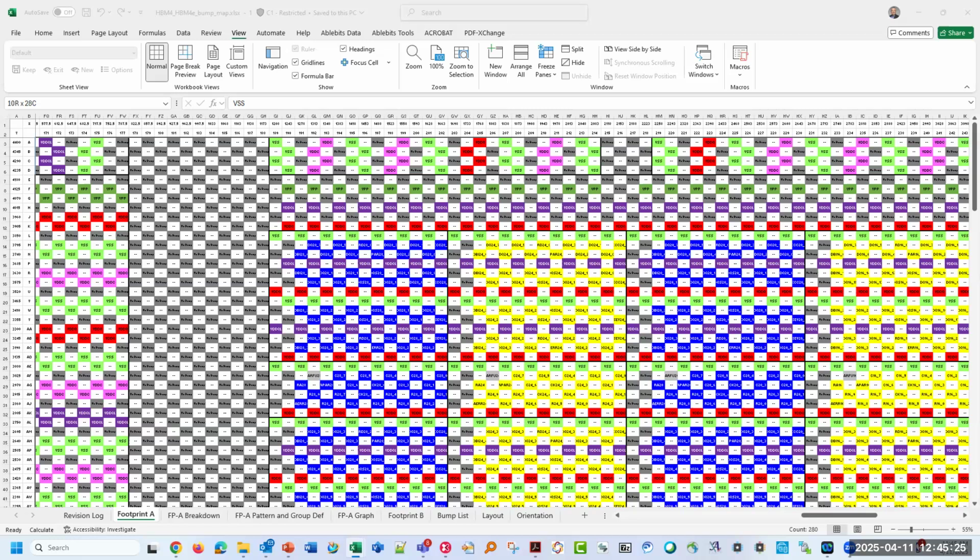But now think of if you had a reroute layer between die 1 and die 2, and you did not have that specified in the part model, then you could be inherently failing your stack up because you don't know of the inter-routing layer and you don't have the routing layer defined. It might be defined in a different file, and that's why I'm saying in the index for the stack, do you want to have the routing layer defined?